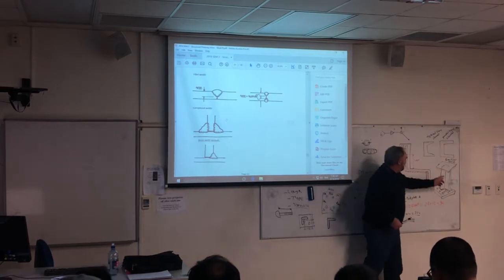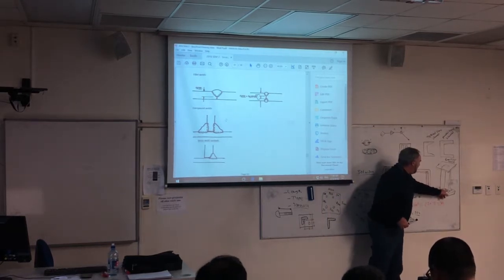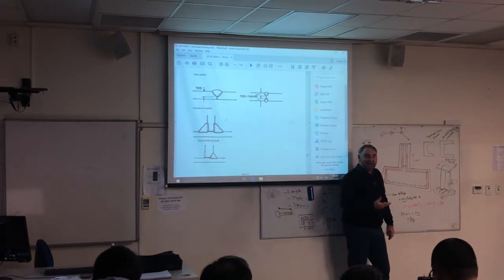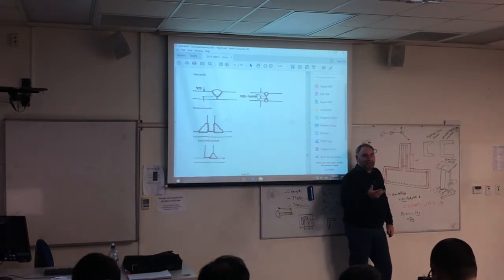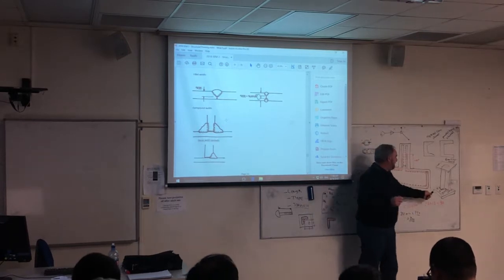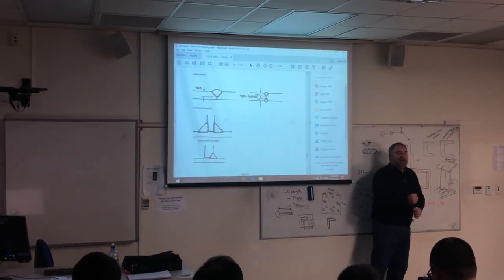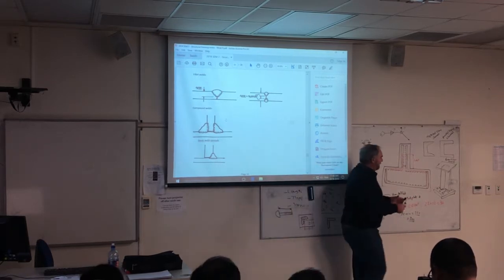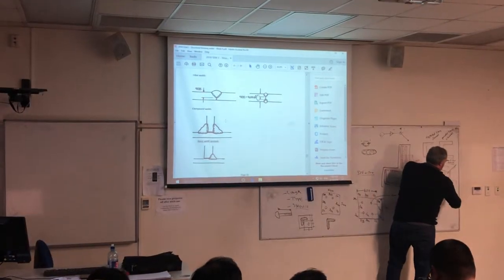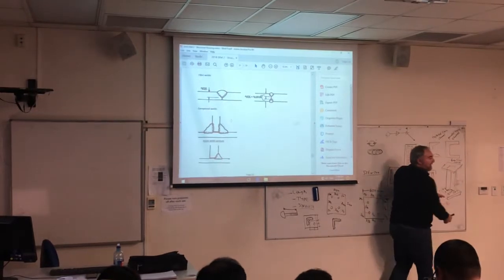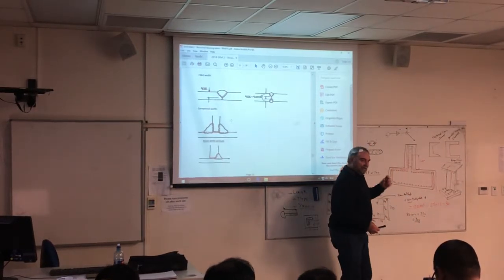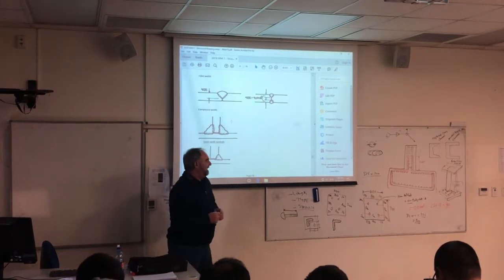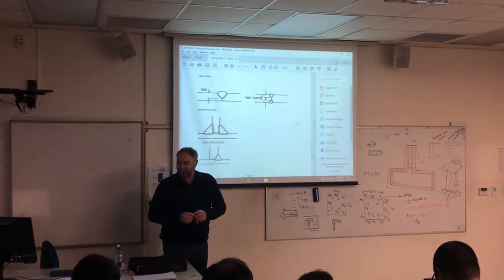So I would say from there, allow 6mm, plus maybe another 6 to 8mm. So let's call that 15mm minimum away from the angle, so you can tighten up the nut. So although your minimum and maximum are taken to the edge of the plate, you still have that restriction of keeping a good 15mm away from the angle.